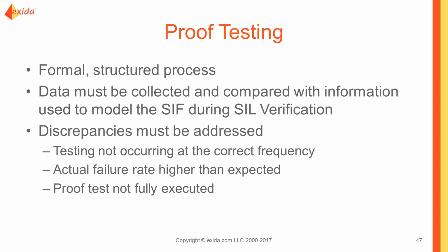I've worked with customers on projects where they had two process trains, with a large safety ball valve in each train. Within the first month of commissioning, they sheared the stem off of each ball valve. That's a sign that maybe the breakaway torque was more than the people who integrated the assembly thought, or the stem strength was lower than they thought, so they put an actuator on there large enough to break it free, but the breakaway torque was higher than the shear torque the stem could take. Those are real issues that exida sees with their clients often. So capturing those types of failures is very important to feed back and correct the loop.